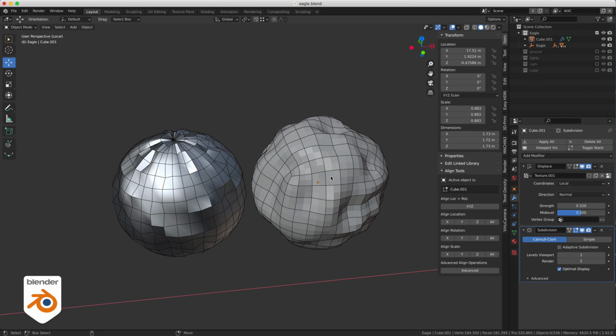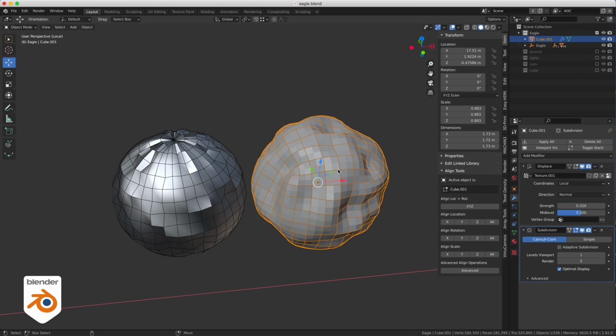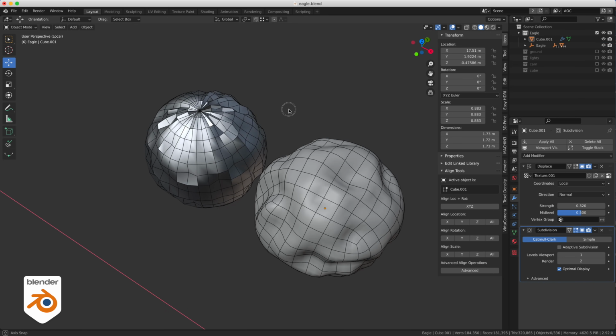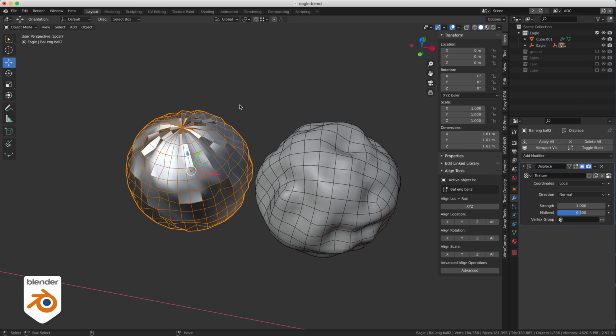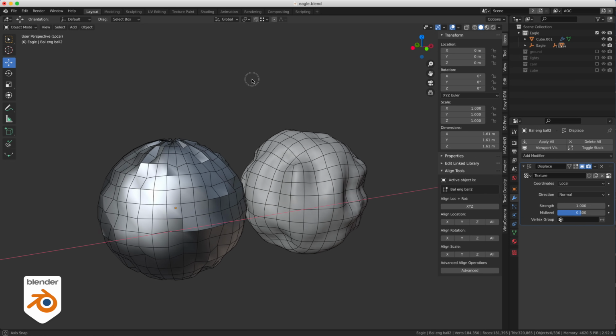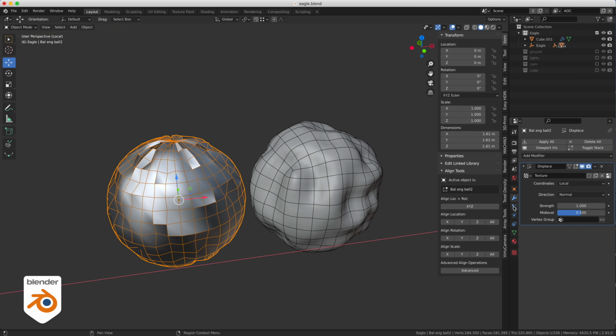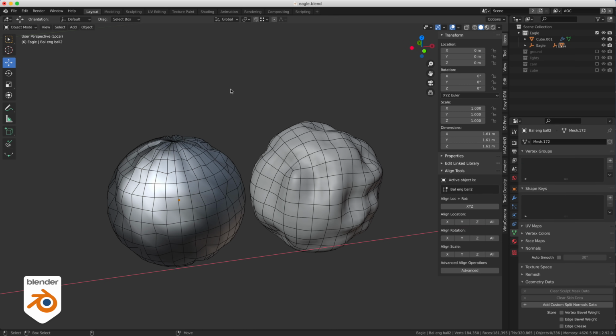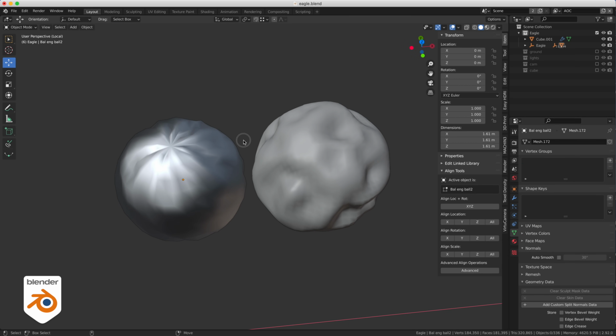Well, first I need to select it before I smooth shade it. Select it, smooth shade it. All right. So you see, you get something that's much more consistent with the other one. Also, the one I made from the cube is going to be easier to texture because we can do the UVs according to the original cube, and we're going to have much less distortion because we won't have to deal with that pole again. So don't anyone dare to tell me I don't know what I'm doing.